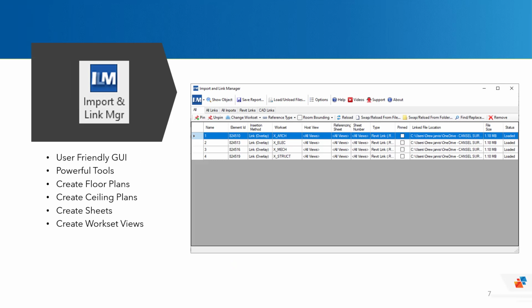Now the Import and Link Manager is going to make a brief appearance, and it'll be there to simply repath a bunch of links rather than having to select each one and then repath it. However, this tool is very useful for keeping an eye on your project health. It enables you to search and destroy CAD imports.